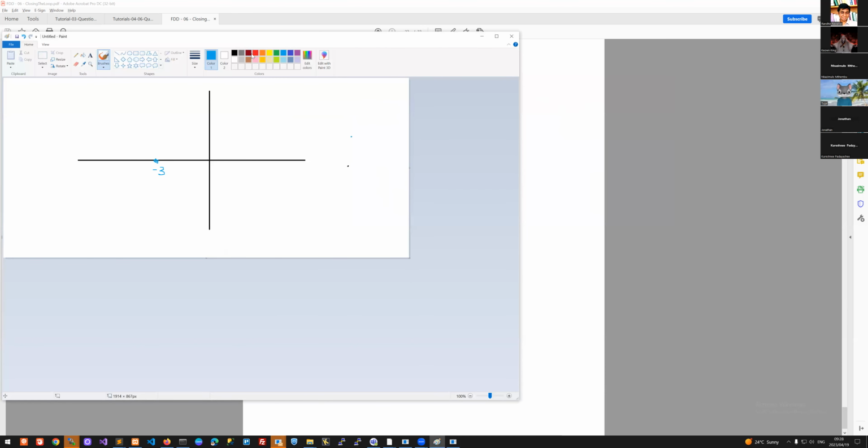So it looks like our first line is approximately like this. So the first asymptote, and our center of gravity is here. So our first asymptote will eventually end up moving along that line. Then the next asymptote is on pi. So that's the next one. And then the last one is on 5/3 pi, which is the complex conjugate of the upper one. So that's the other asymptote.